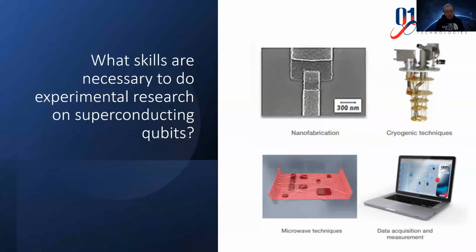And the photolithography is used to fabricate the components with a larger size, such as microwave resonators, transmission lines, and those kinds of components. In electron beam lithography, an electron beam is used to write the patterns instead of UV light as in photolithography. After developing the pattern, the aluminum is deposited using thermal evaporation or e-beam evaporation techniques.